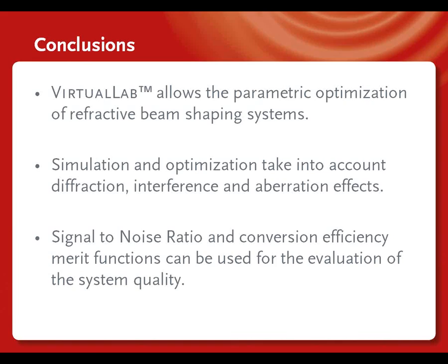And it will use an analytical geometrical optics approach to calculate an initial guess of the surface profile of such a cylindrical or aspherical or freeform surface. And in this case, the parametric optimization is just used to make an improvement of this initial guess to reach a little bit higher efficiency and SNR, but typically this will reduce dramatically the calculation time and the number of iterations that are required. And so we will show this in another seminar as soon as it is available.